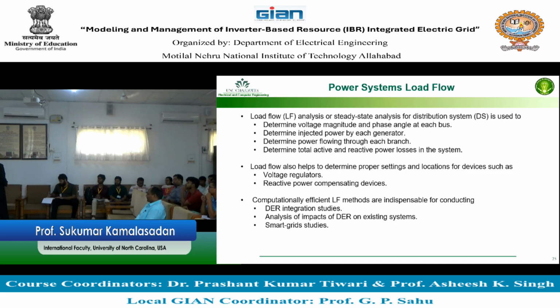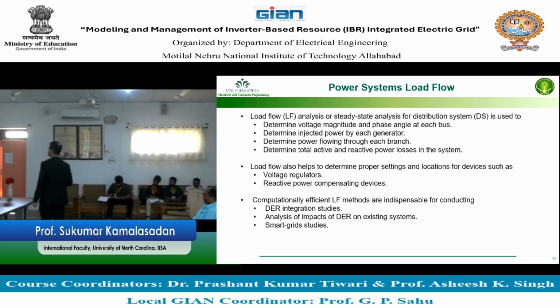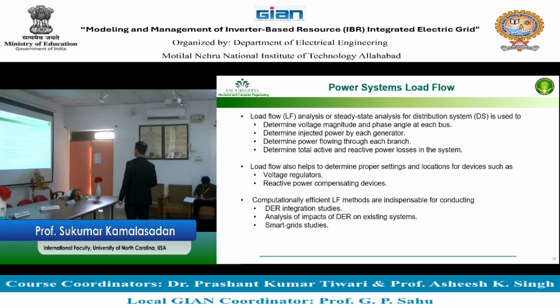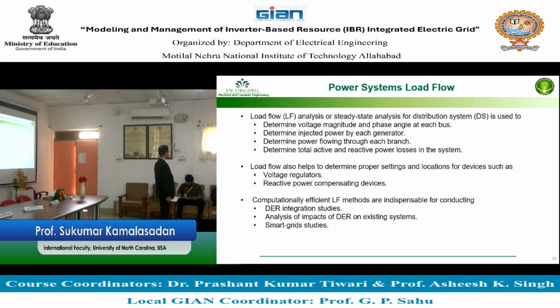So the main two objectives of the power flow are the voltage profile and the losses, along with not having enough generating sources. If you do not have enough generating sources, obviously it will not work. But fundamentally, these are the main two things that you will want to know from the power flow. So power flow is used for planning purposes, and some of the things are written here.